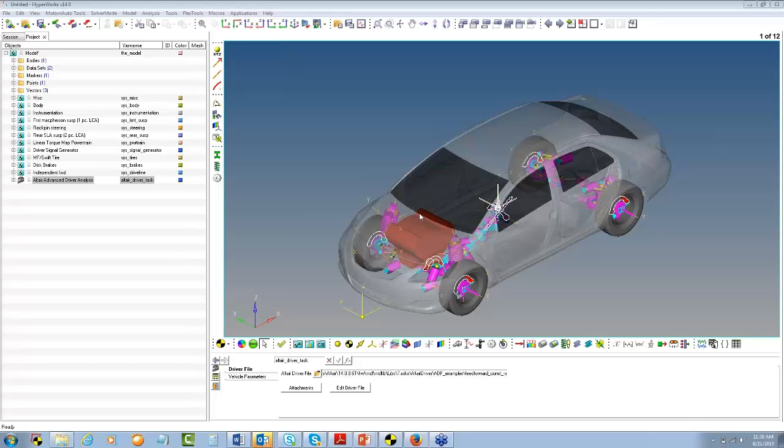Is there any relation between the length of the vehicle and the suspension system? Of course, there is a relation. Your transient response of the vehicle is affected by the polar moment of inertia of the vehicle, which is directly affected by the length of the vehicle. So the longer your vehicle is, the more its polar moment of inertia is. Of course, its turning radius would be high, and because the inertia is high, it would make it hard for the vehicle to turn as well.